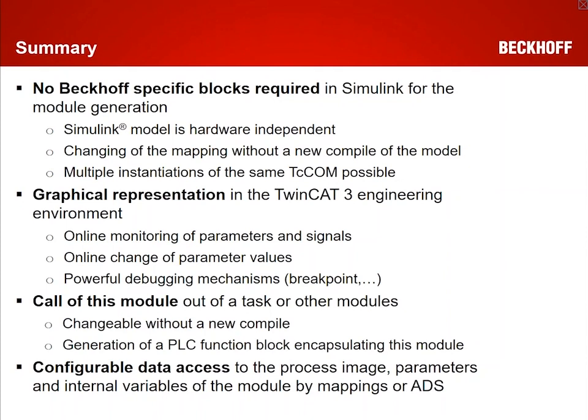And what we also have is that if you want to change the mapping of inputs and outputs in TwinCAT, you don't need to do a recompile. If you need to specify the mapping in Simulink, then every time you would need to do a recompile of the model because you just want to map the outputs or inputs to another output or input source.